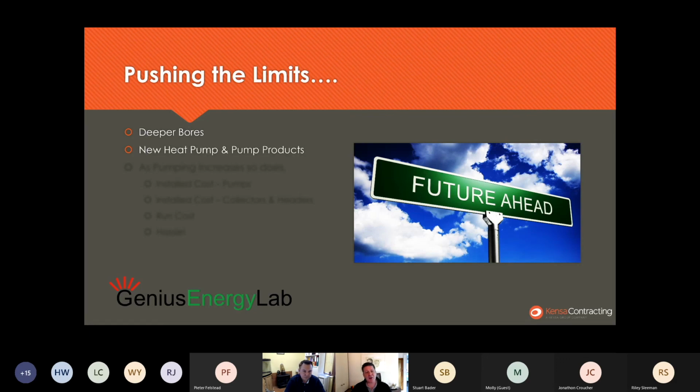New heat pump products are definitely worth mentioning. We're involved in the new innovative products that are coming on stream from Kenza, and we're really excited about that. But I'm anxious to see what the flow rates are like on these things. If you're chasing the ultimate efficiency, you're almost always going to have bigger heat exchangers, with a bigger surface area, which will generally be flow rate hungry. So they'll be looking for higher flow rates on those systems, and that could drive you into pressure drop problems.